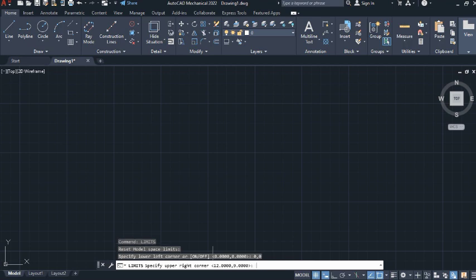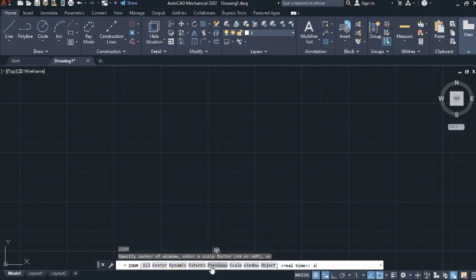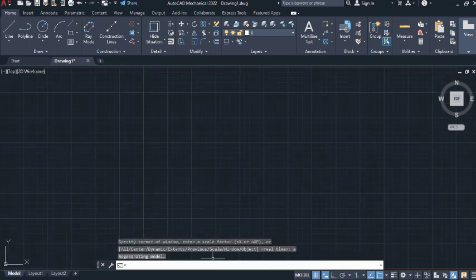Then for me, I really specify we use 100 and above, although for most of my building drawings and structures I use about 20,000, 50,000 boundaries. So let's use 100 for the sake of this tutorial. We go to our keyboard and type 100,100 and hit the enter key, Z for zoom all, and A for automatic, just like that.